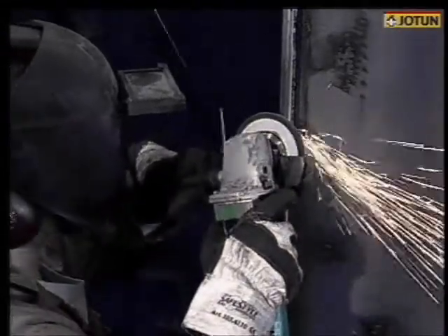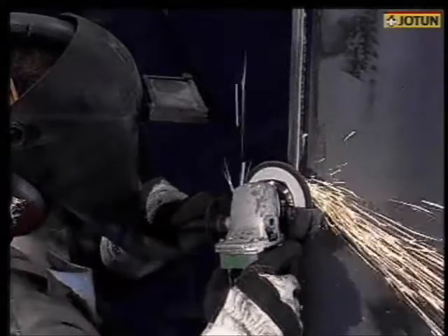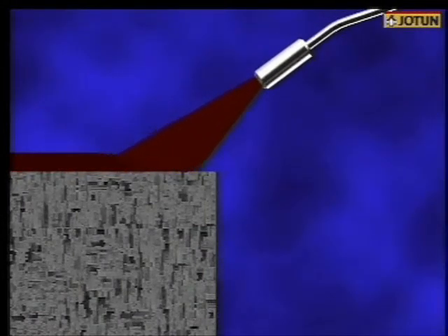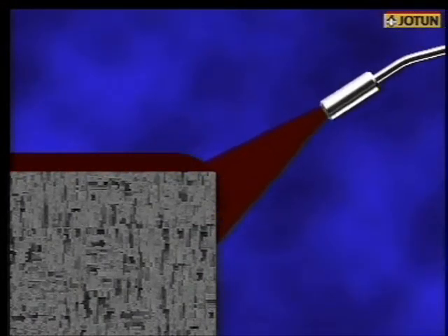Corrosion often starts at sharp edges. The reason for this is that the specified dry film thickness is not achievable around sharp edges. Prior to pre-treatment and painting, such edges must be rounded by disc grinding. A reduced film thickness will give a lower barrier effect, and corrosion will initiate much earlier than on plain surfaces.